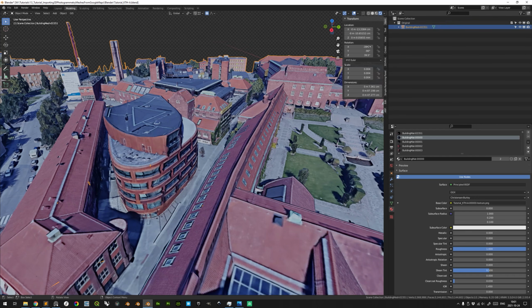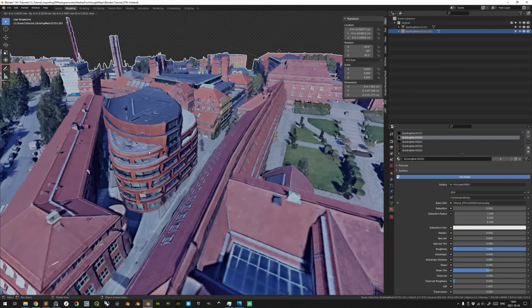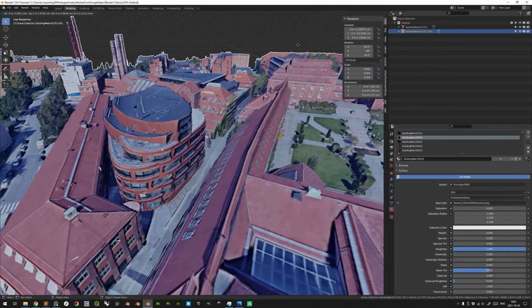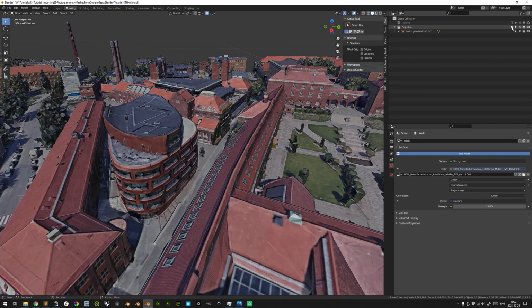Okay, very good. And then with this still selected, we can hold Shift and press D for duplicate. When you see that the duplicate object moves, you can simply cancel the positioning with a right mouse button click, and it will be in the same place as the original. With this duplicate still selected, we can press M and create a new collection called projected. Very good. Now we have two different collections, the projected and the original.